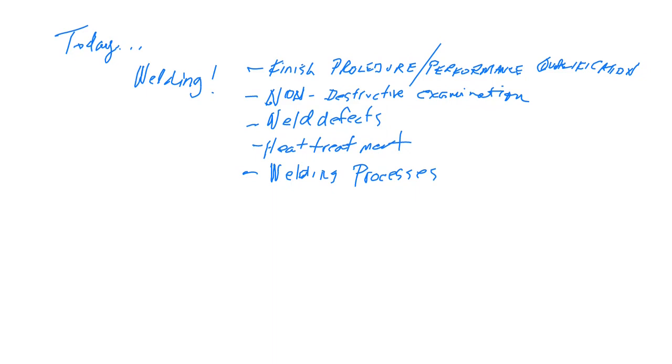And you'll notice if you look at the chapter questions in the back of chapter 14, question number 7 is describe the following terms. Welding procedure qualification. Well, you know what welding procedure qualification is all about. It means you have to make a weld procedure specification, then you have to have evidence that the weld procedure works, which is the procedure qualification record. And the other part of question 7 says, define welder performance qualification. And that's what we started off, and I think we kind of ended off there.